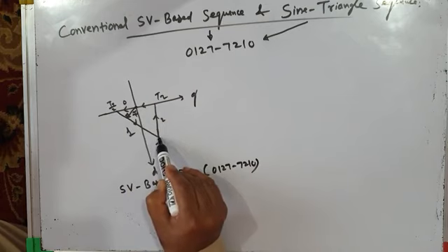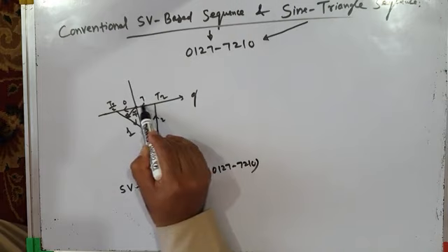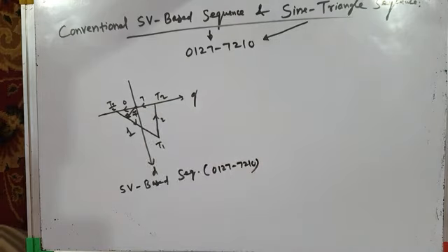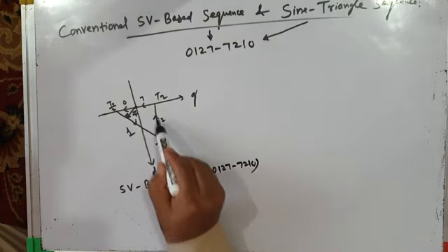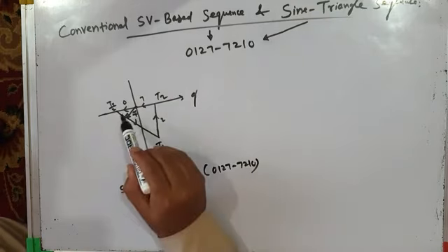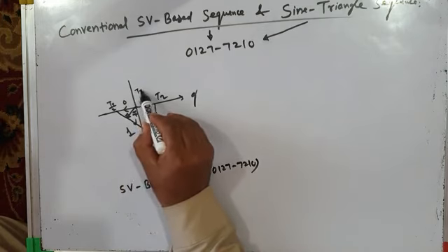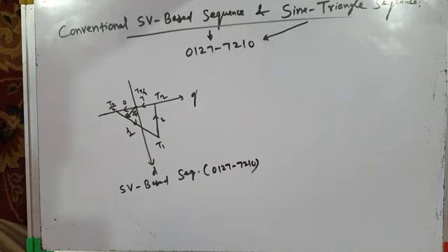When active vector 2 is applied, it moves along this line. When null vector 7 is applied, it moves. So that completes the subcycle. It starts from origin, traces this triangular path, comes back to origin. And you can very interestingly see that the time interval between null vectors 0 and 7 is equal. So it is Tz by 2 here, it is Tz by 2 here also.